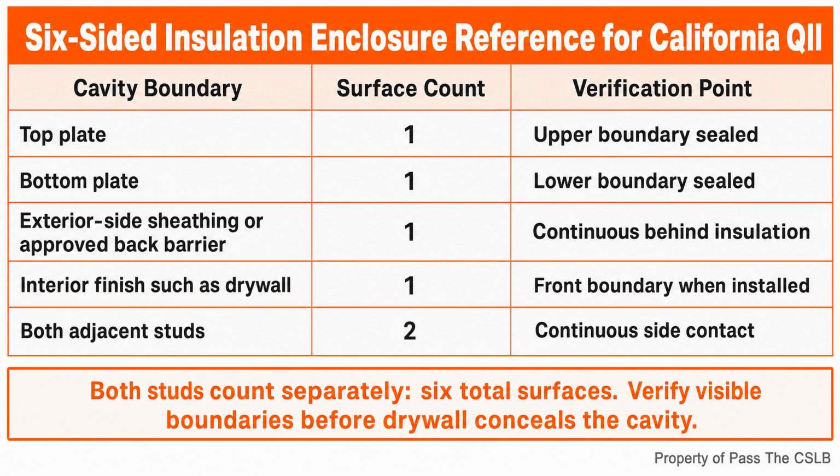That distinction becomes important at drop ceilings, chases, knee walls, and other concealed transitions. A hard cover or draft stop made from a suitable solid material keeps insulation in place and blocks the air path.